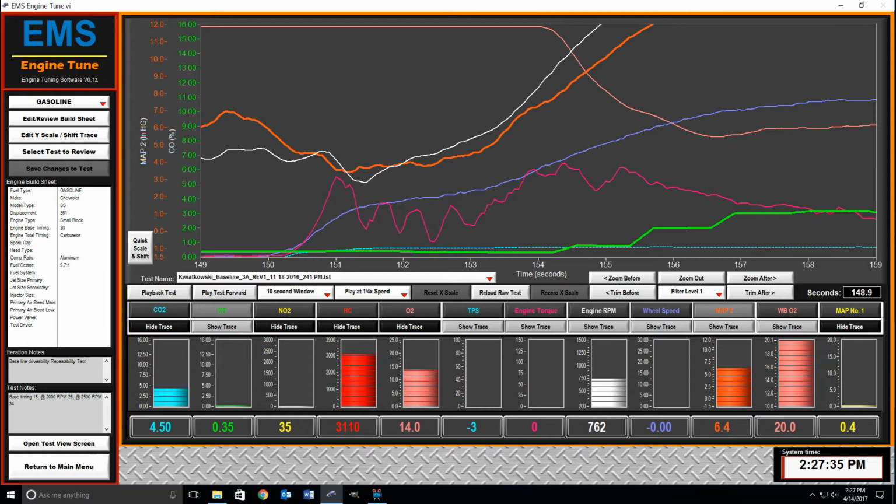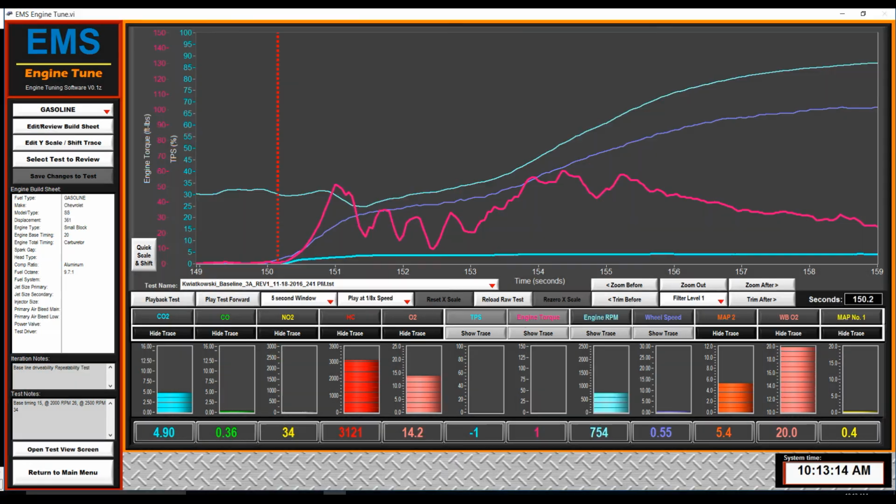We also have a condition that's occurring which is called acceleration of the vehicle. So we will need an increase in the amount of fuel to help us drive more torque. To be able to achieve this additional torque, we will also need to move the throttle plate, increasing the amount of air that is going into the engine so that we also will generate a higher combustion pressure.